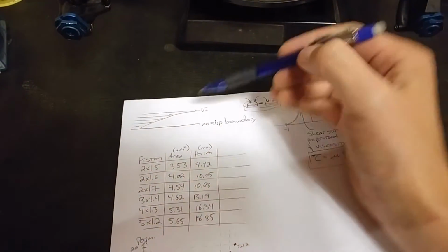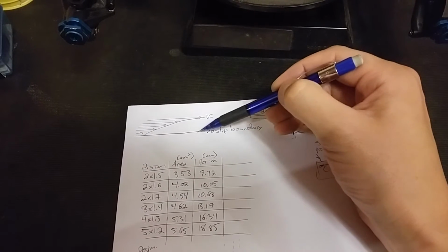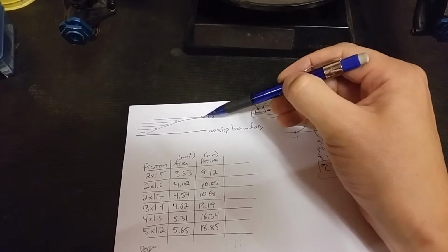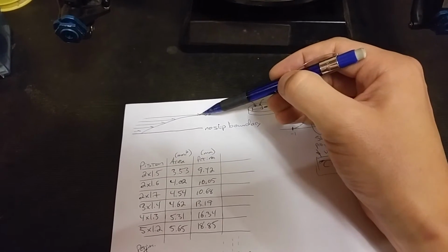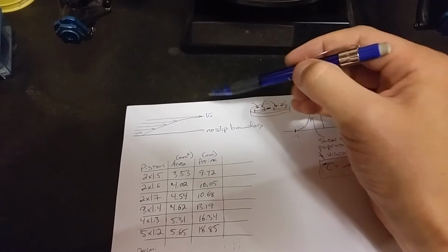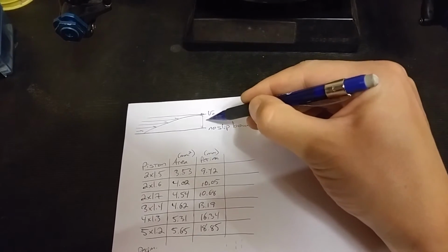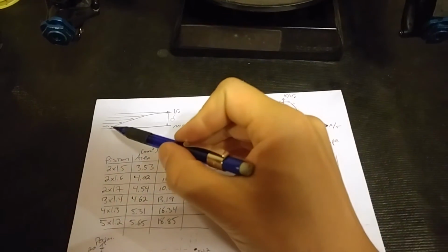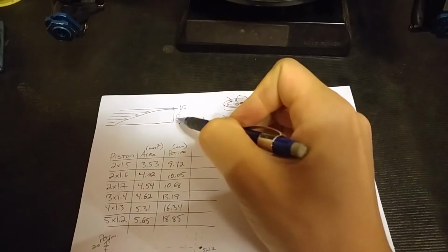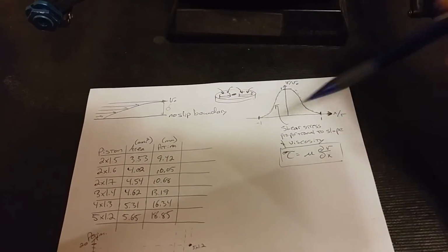Okay. Now, this distance between this no-slip boundary, this surface here, and some point in space where we have velocity that's substantially the same as the free velocity, this is called the boundary layer, typically expressed as a term delta. Now, the rate at which this velocity changes as you move away from the surface will affect something called shear stress.